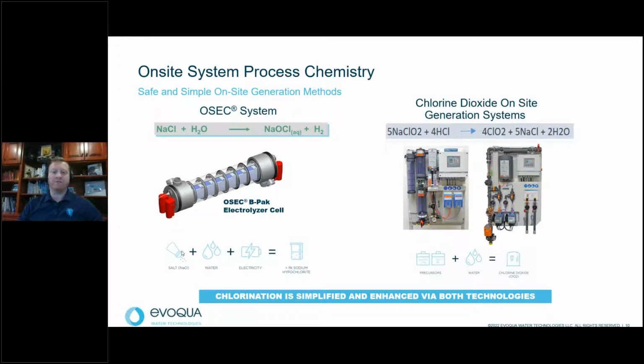Chlorine dioxide can be formed in a few different methods and will vary from manufacturer to manufacturer of chlorine dioxide equipment. The method we feel is best suited for the beverage industry mixes sodium chlorite and hydrochloric acid, with a theoretical efficiency of about 80% related to the sodium chlorite input, and with about 95% conversion of the mixing.